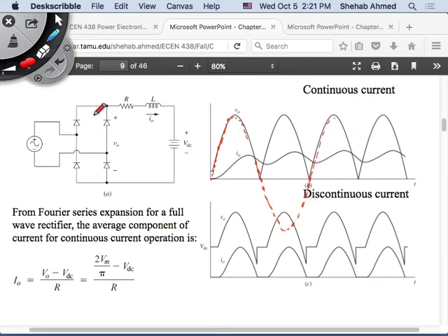Right? This is a full wave rectified waveform. We agree? It's a full wave rectified waveform? So here I will see a full wave rectified waveform. Here, if the voltage on this side is less than the voltage on this side, is current going to flow? Remember, current flows from the higher voltage side to the lower voltage side. So, if the rectified waveform has a higher value than my DC source, then current will flow.